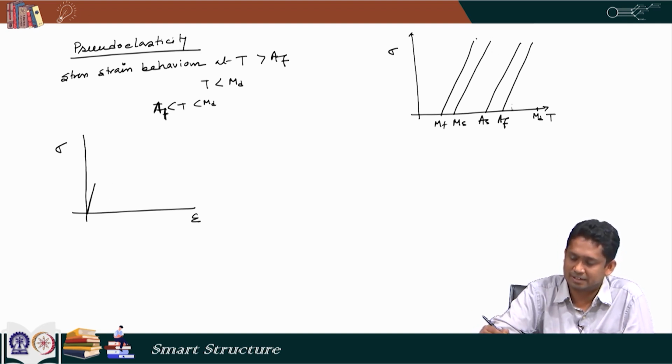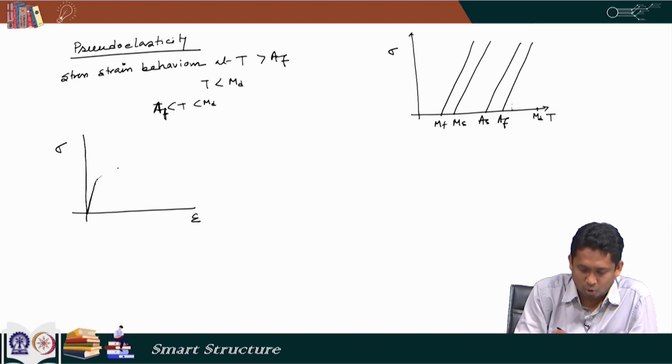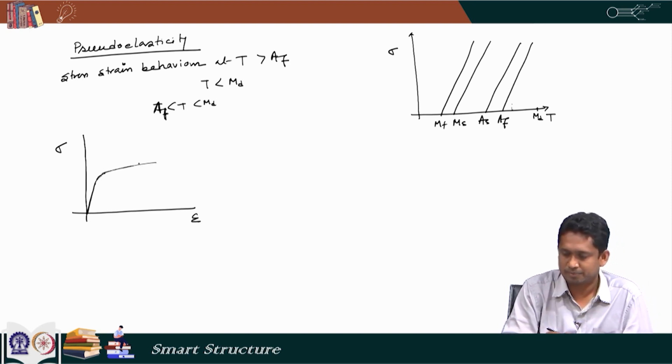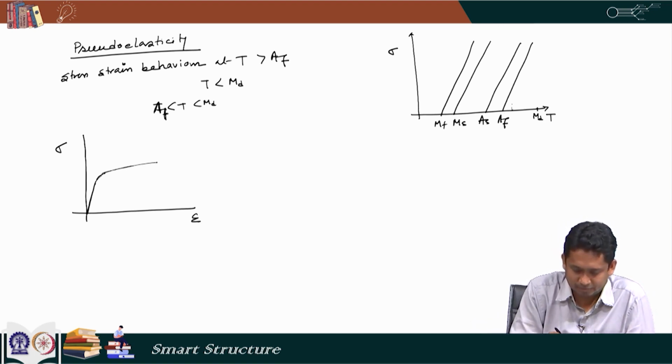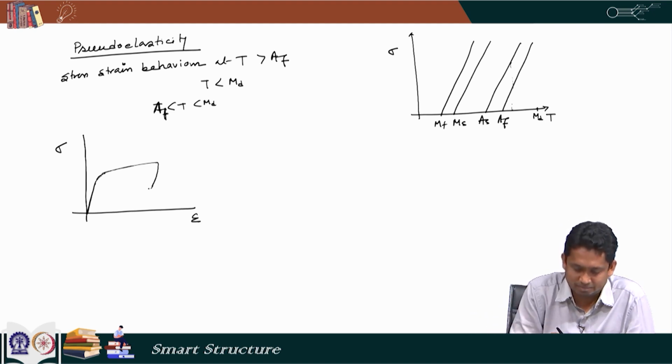Once it crosses these lines, the material starts becoming stress-induced martensite, and then the slope of the stress-strain curve changes and becomes very close to 0. From there, if we unload it, initially the relation is linear, and after that, while unloading, once it crosses these regions in the downward direction, the austenite transformation takes place and it is recovered quickly. So, that is how the diagram looks.